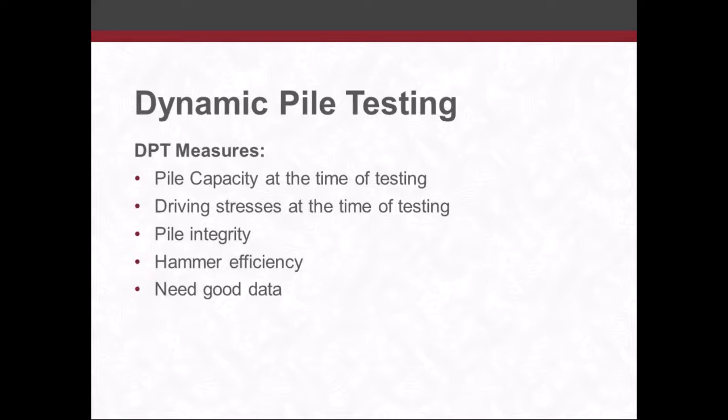We're also monitoring pile integrity, if there's any damage or potential damage going on, and the program will indicate the location as well as any general severity of damage as the pile is being driven. Also monitoring hammer energy and how well that hammer is operating compared to the rated energy for the hammer. And in any event, we need to make sure we have good data. If we don't have good data, then all the other results are going to be meaningless.